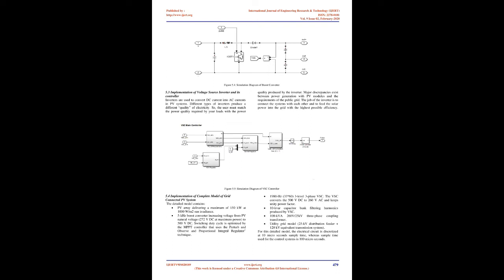The methods have certain advantages and certain disadvantages. The choice of which algorithm to utilize depends on the need and the operating conditions. For example, if the required algorithm is to be simple and not much effort is given to the reduction of the voltage ripple, then P&O is suitable. But if the algorithm is to give a definite operating point and the voltage fluctuation near the MPP is to be reduced, then the IC method is suitable, but this would make the operation complex and more costly.